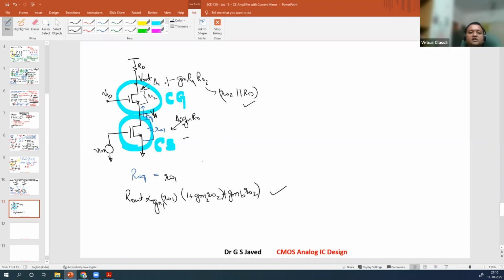So what is important here: common source followed by common gate. Common source followed by common gate, you will see what is the gain transmission. Common source inversion will happen here. So your input is inverted at VA. So it is minus GM Vin. So this minus GM Vin is given to that source, and that literally gets translated to the output multiplied by the gain factor. So minus GM Vin times R out is what you will get there. So one is inverting, another is non-inverting. So you will have a slightly larger gain.